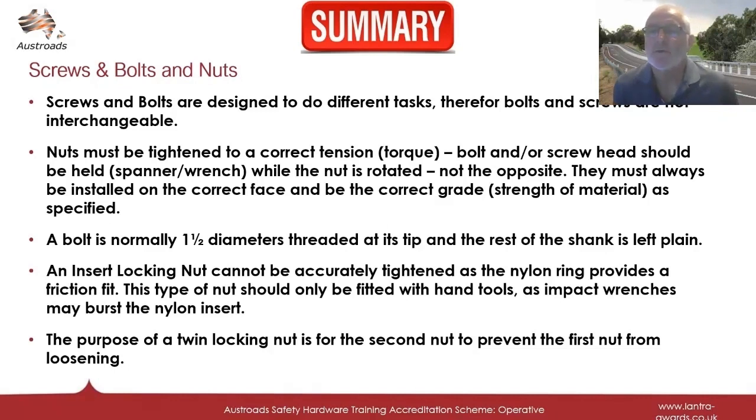Summarising, screws and bolts are designed to do different tasks. Therefore, bolts and screws are not interchangeable. Nuts must be tightened to the correct tension, torque. The bolt and/or screw head should be held with your spanner or wrench while the nut is rotated, not the opposite. They must always be installed to the correct face and be the correct grade, as specified.